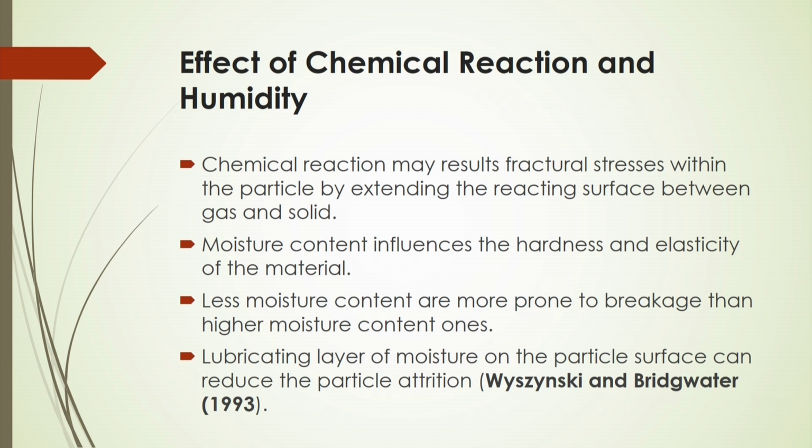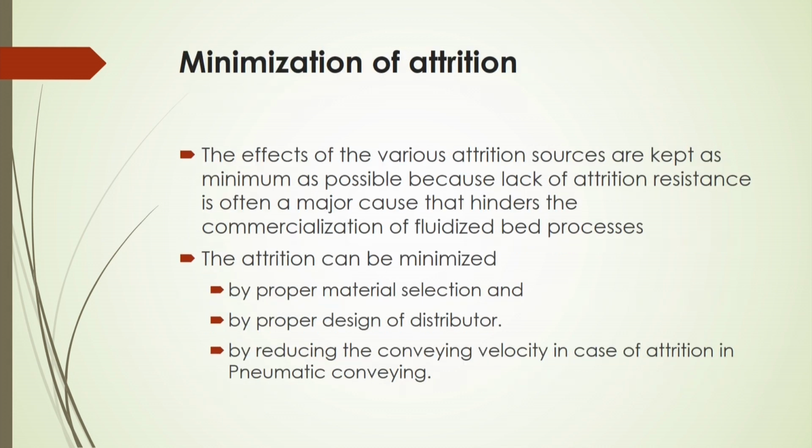Of course, if more moisture is retained in the solids, then the impact of particle collision will be smoother. The surface will be smoother, and because of that the attrition rate will be less. A lubricating layer of moisture on the particle surface can reduce particle attrition. Now, of course, during the operation of the fluidized bed,